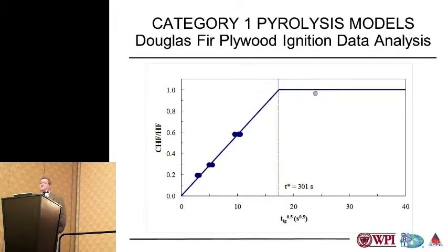All right, first question, if you want to recreate, or if you want to use that information from tests at different heat fluxes to determine what the ignition time is in the actual room scenario, you would need to interpret the data in terms of material properties like thermal inertia and ignition temperature. When you scan the literature, you'll find about a dozen methods to do that. In the guide, we're really only focusing on two different methods.